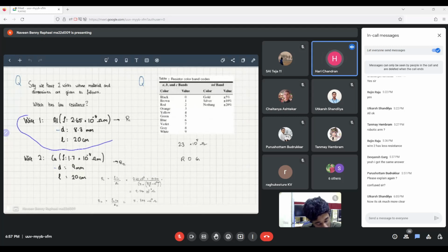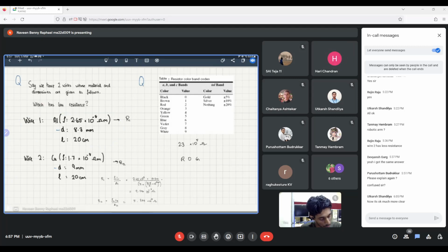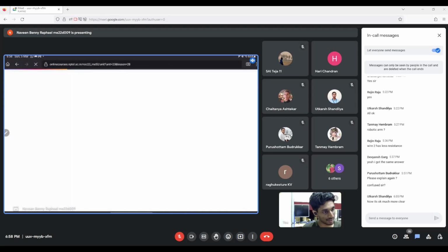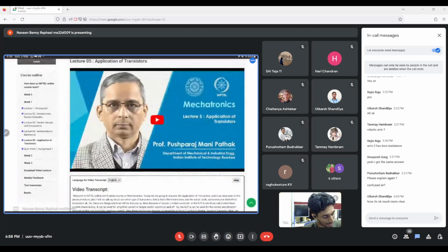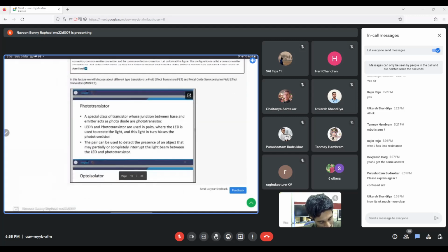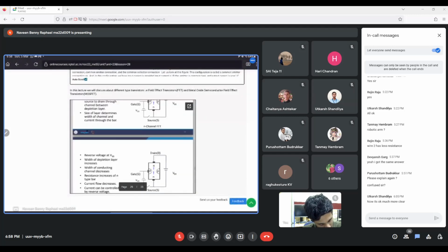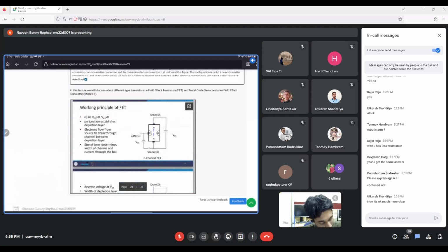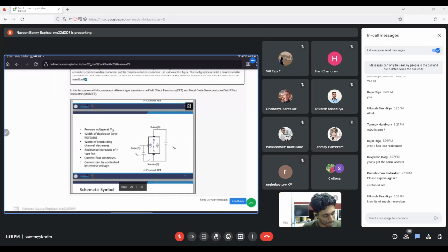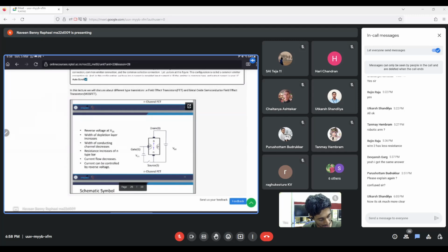Can you clarify how FET and bipolar differ? I pointed it out earlier, right? Yeah. Essentially, they are completely different technologies. FETs are made using this specific arrangement, as in you have an N-type semiconductor and you have two regions of P-type semiconductor in it, and this is done by methods like etching and things like that. And this is the N-channel FET.